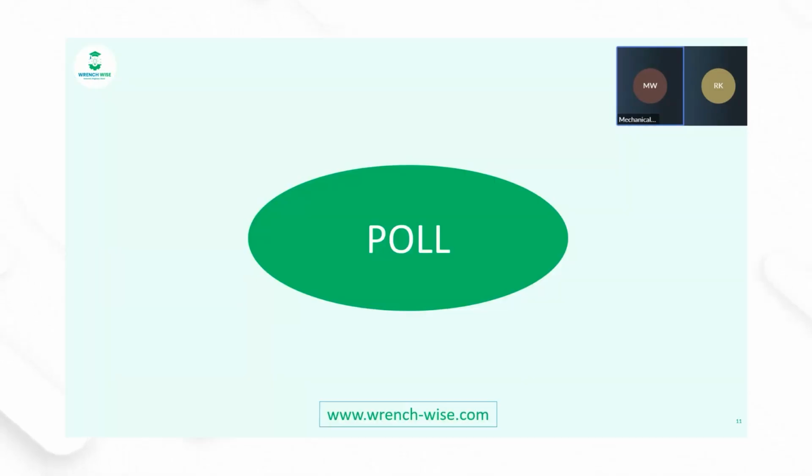What is the thermal conductivity disparity ratio between the battery's highway and the wall, the aluminum foil versus polymer? Correct, this is 1000 to 1. So again, I'll just very quickly talk about it. Using a single scalar number, k equal to 20, is mathematically averaging your thermal properties, leading to a very high percentage of over-prediction of your radial cooling. So we should not do that, is the point.